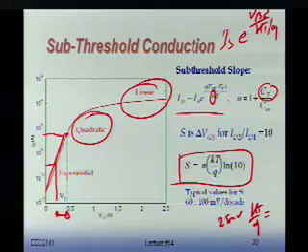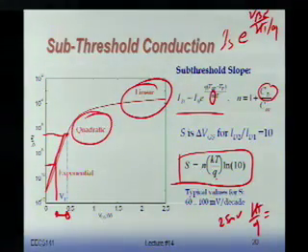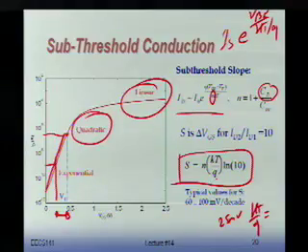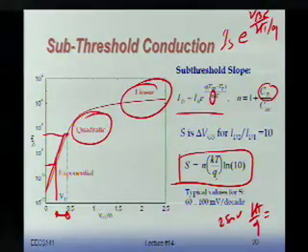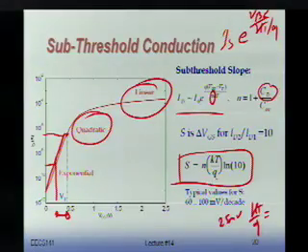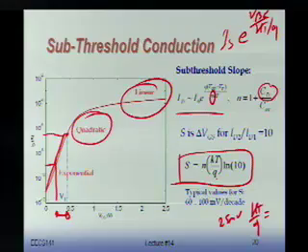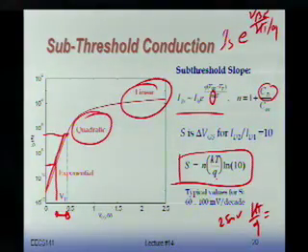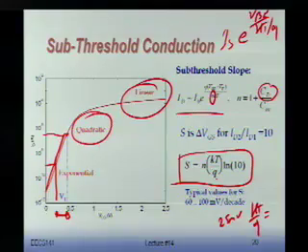Okay? You just take this thing here and you put 1 in here. 25 millivolt times ln10 gives you approximately 60 millivolt. So every time, suppose my threshold is 0.4 volt, I drop my voltage 60 millivolt below the threshold voltage, my current is going to go down with a factor 10 in a bipolar device. Good. And do another 60 millivolt, I get another factor 10.